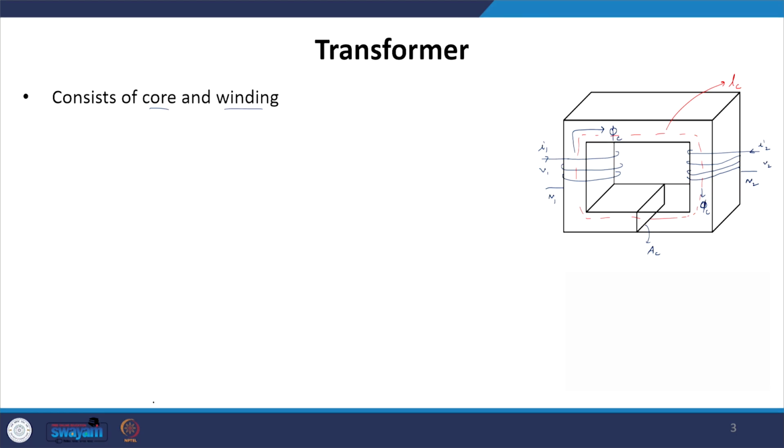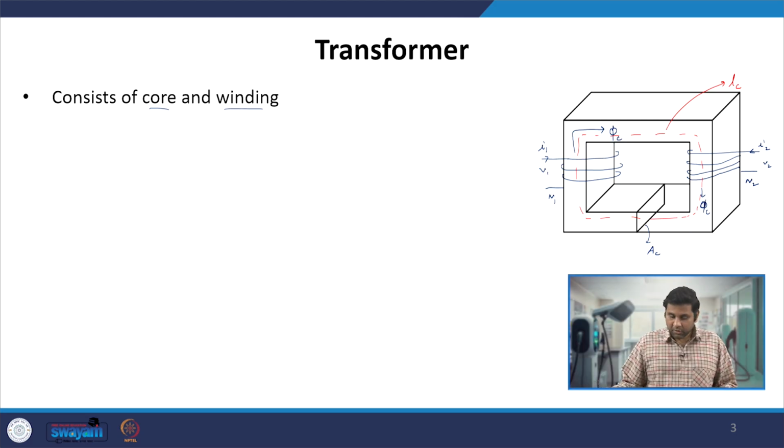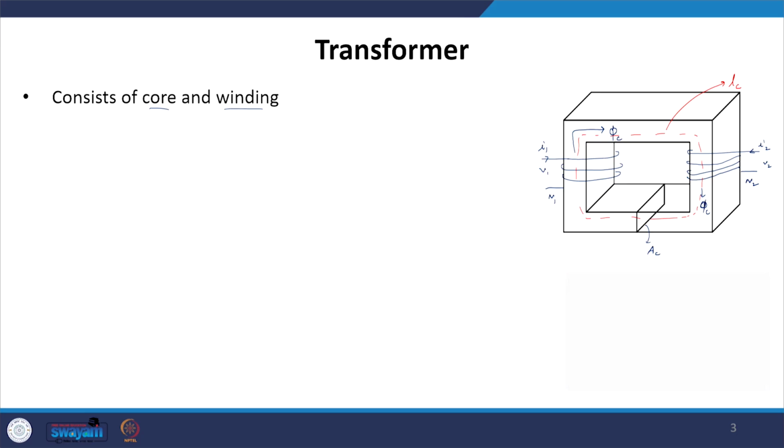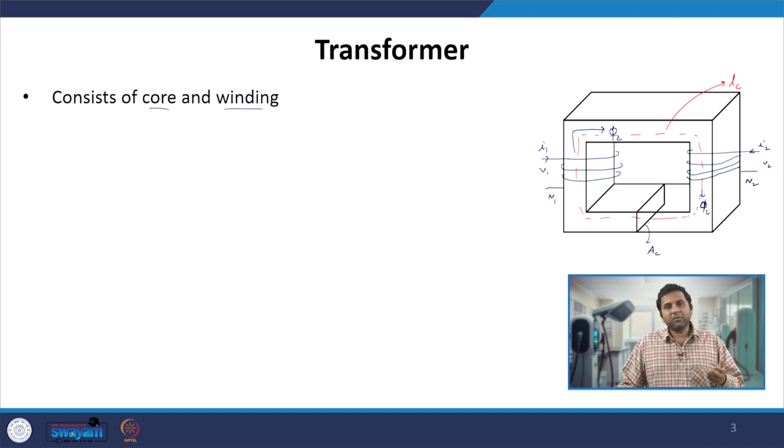Now in this particular type of setup, we are applying an excitation current into one of the windings. We know that the core material is mostly made up of ferromagnetic material, which consists of magnetic domains, and whenever no external magnetic field is applied, those domains are arranged in a random manner. As a result, the net flux generated by those domains, because the domain itself produces magnetic flux,